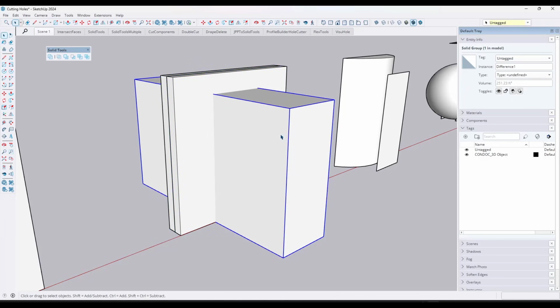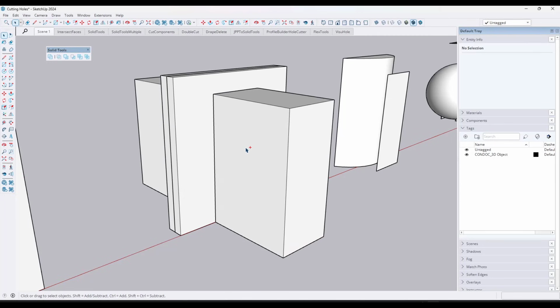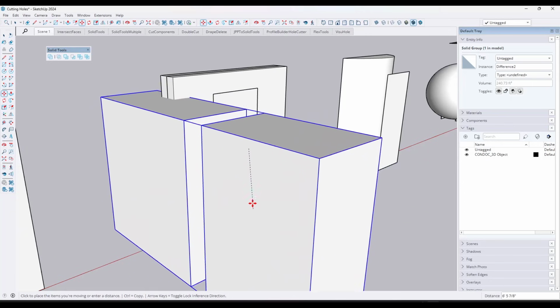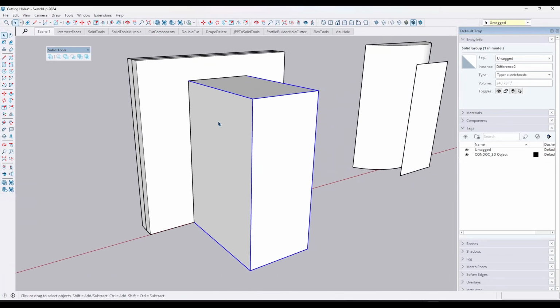So we're just going to activate this object right here. We're going to click on split, or we're going to split the second object. And we're going to do this twice. So we're going to use it to split both of these objects. And then when you delete this out, notice what that did is it basically split out the geometry anywhere anything intersected like this.